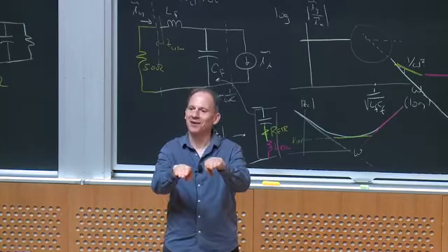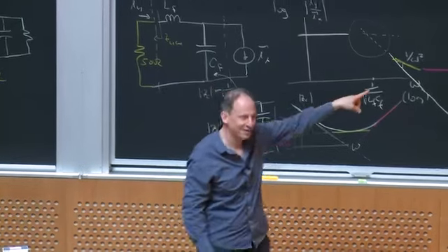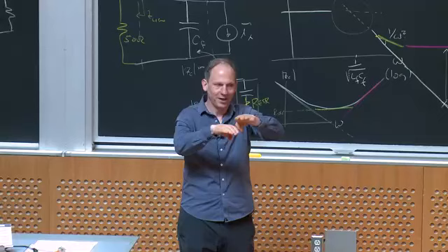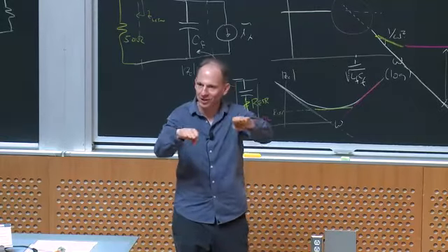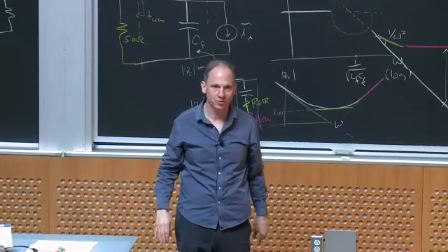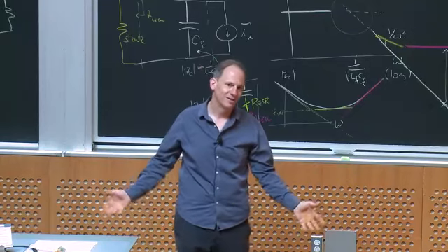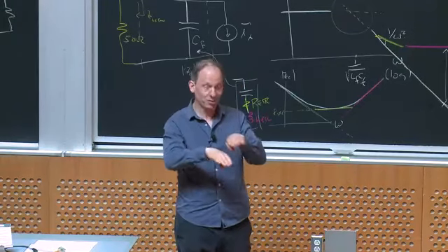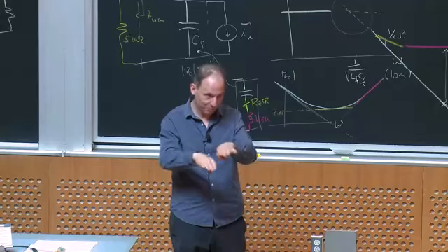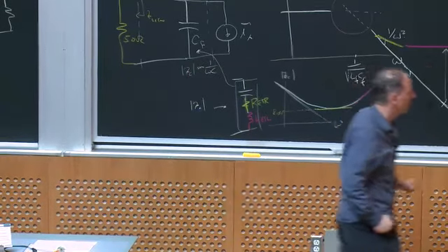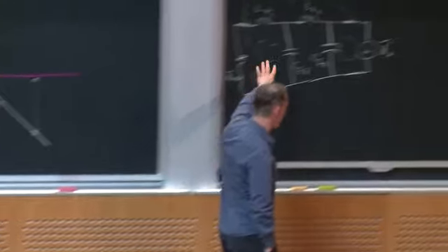Suddenly we were passing it fine. It was exactly that phenomenon. There was a noisy port that was too close to the input, and we were capacitively coupling energy into the input. And all we had to do was move the trace. And that parasitic isn't showing up in your schematic. It's not showing up anywhere, but it's there in the real world, and you have to go find it. We moved that one plane, and we were fine. Okay, so you have to spend a lot of time thinking about this.